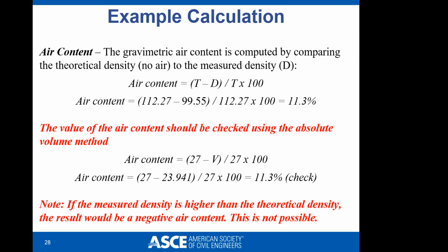And again, here, we just highlight in red that if your measured density is greater than the theoretical density, you will get a negative air content. And again, you do need to do both calculations as a check to show that you're doing it correctly.